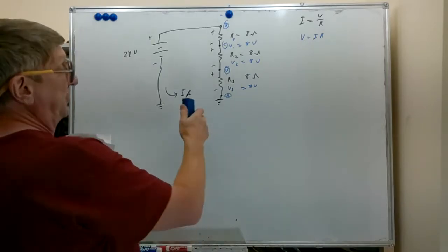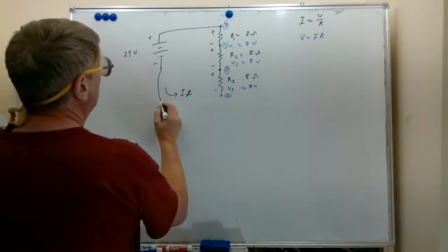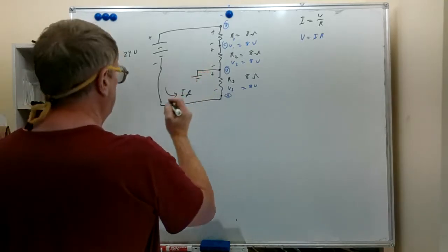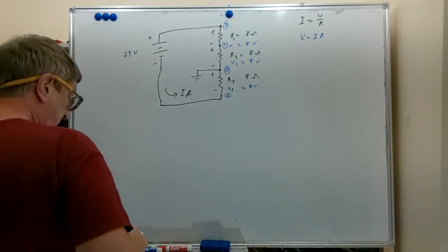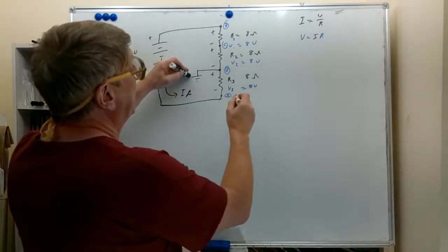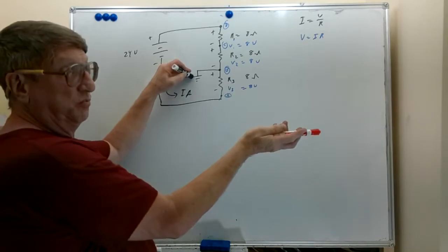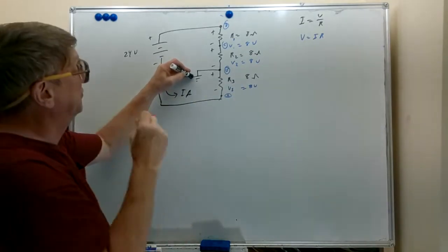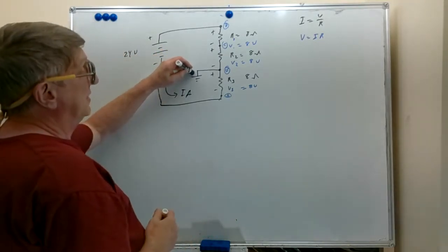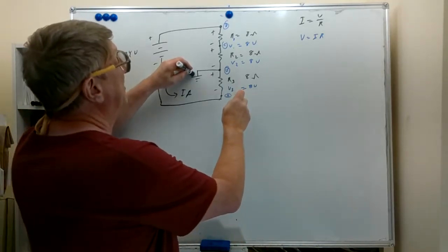There are other possibilities. This is a common way of seeing things done, but there are others. If we connect our wire here and put our ground on point B, what happens when we start reading things? Well, we'll put our probe here on ground. If we read point A, we went down 8 volts, so we're going to see negative 8 volts. A lot of meters nowadays will swing both ways or show you a negative or positive indication. So if you put your ground lead on point B or on the chassis of the radio or whatever, and read point A, you're going to see negative 8 volts.